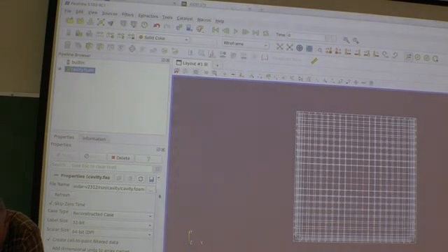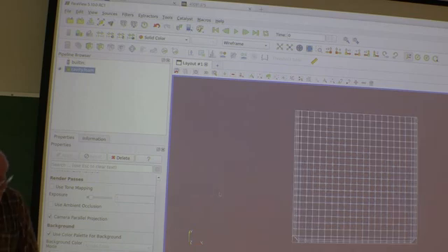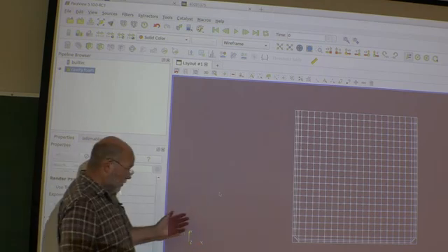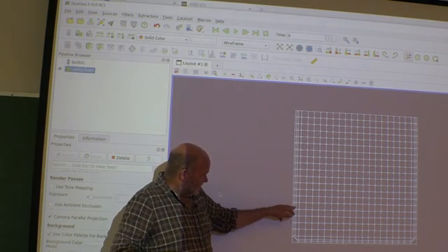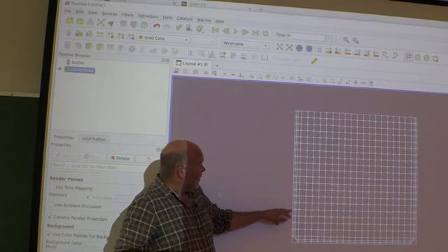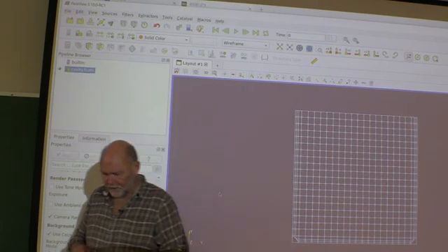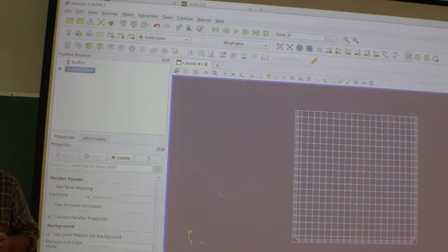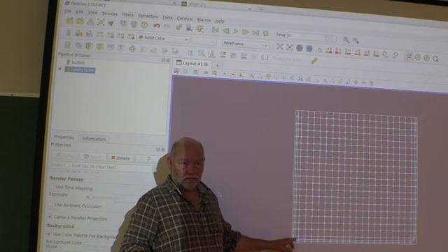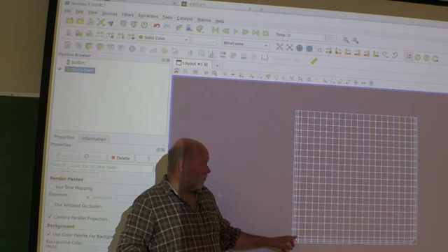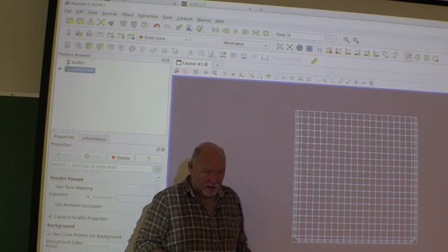Wireframe and the parallel projection. So there you see what he has done. It was 20 by 20 uniform, and we have split the closest cell in half, and then that cell also in half. But you look at the corners, they don't look nice. We get some messy things there, I don't like it. Not that it's so important. Down here, you hardly have any velocity at all. So it's not crucial. He won't change the overall solution, I think. Still, I don't like it.